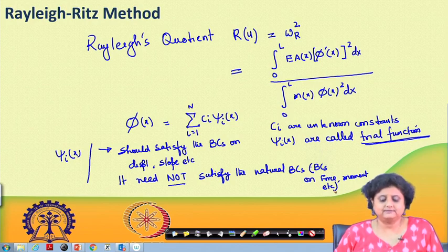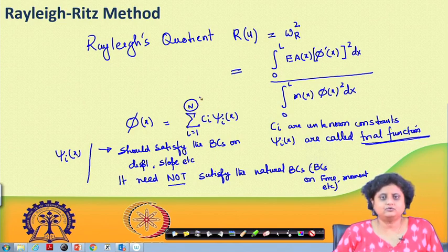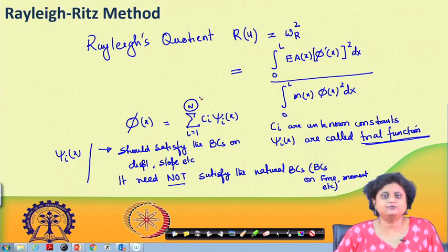This number n denotes how many trial functions we are using. It is intuitive to understand that the larger the n, the better the approximation we are going to achieve. But increasing n also increases the computational requirement of the process, so we always try to optimize n. We always try to take the minimum n to get the best approximated mode shape. This can be done by choosing trial functions which are a good approximation of the possible mode shape of the structure.